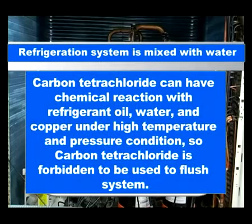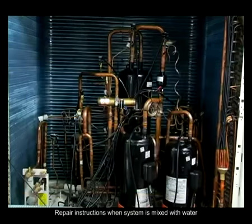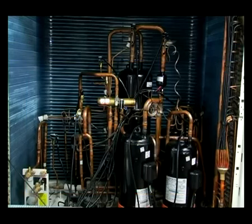Carbon tetrachloride can have chemical reaction with refrigerant oil, water, and copper under high temperature and pressure condition, so carbon tetrachloride is forbidden to be used to flush system. Repair instructions when system is mixed with water.